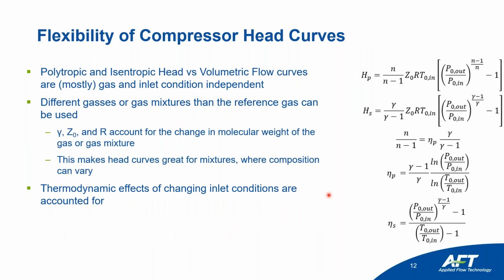So once again, I'm just going to mention that this is as flexible as it gets for compressor curves, at least as far as I know. And that's why it's really important to know these and to get these from your compressor manufacturer, especially if you're dealing with high pressure stuff where the flow is going to be compressible, because that flow is going to change with your inlet conditions.